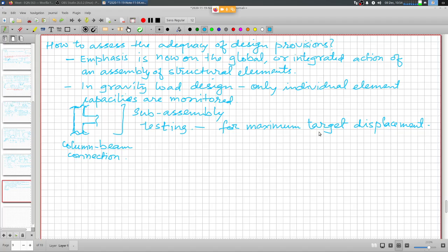So it is not prudent to design elastic, for no damage, for an earthquake which is very severe and which may not even occur during the lifetime of the structure. It is very unlikely that a very strong earthquake will test the structure during its lifetime.